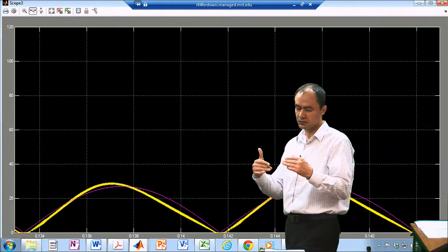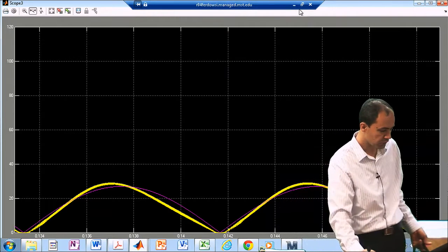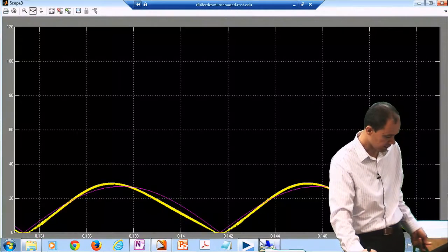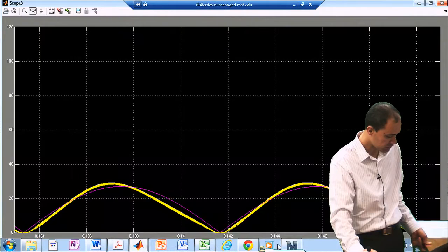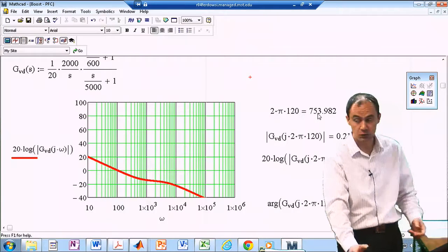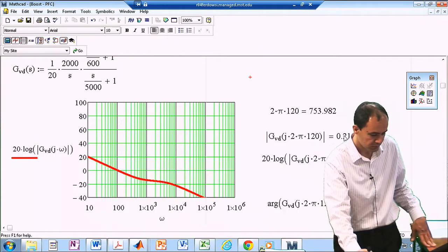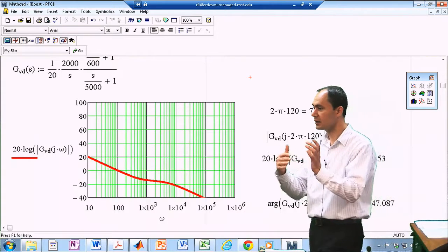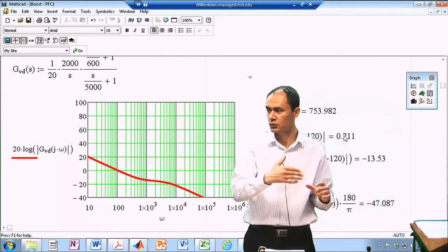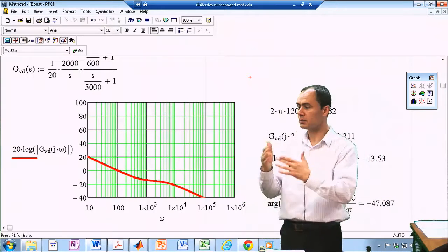This is because before, we had extra attenuation at 120 hertz. It was only 9%, now it is 21%. So you can see that this ripple, if it gets to your controller, it messes up everything because it's being multiplied by everything else.